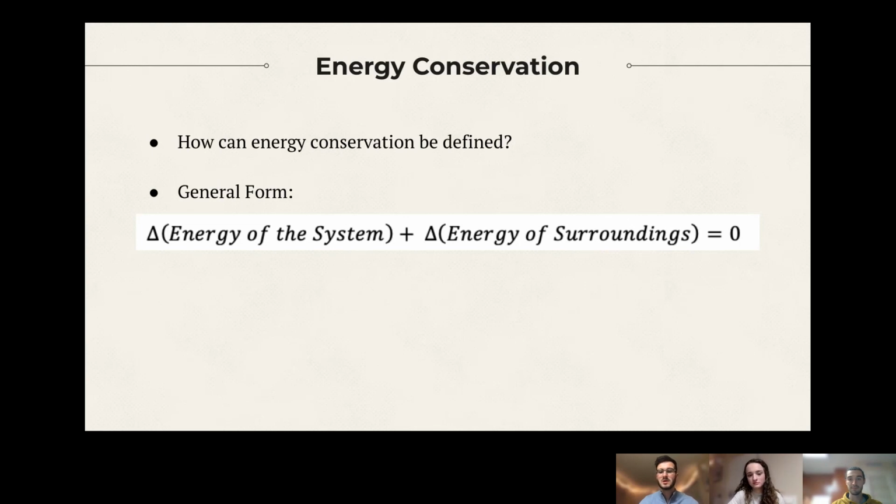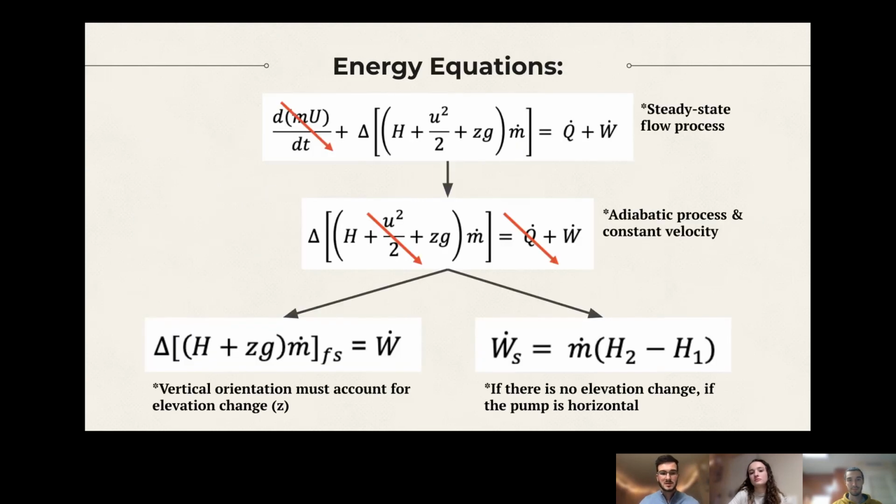It is also important to know whether the system is open or closed. A system is said to be open when matter crosses the system's boundaries, such as steam, or in this case, water, and closed when matter does not cross the system's boundaries. When the system is open, the flow rate of matter must be incorporated into the overall energy balances, which will be looked at next. So as you can see by this first equation, this is the general energy balance for all types of processing equipment and forms of energy.